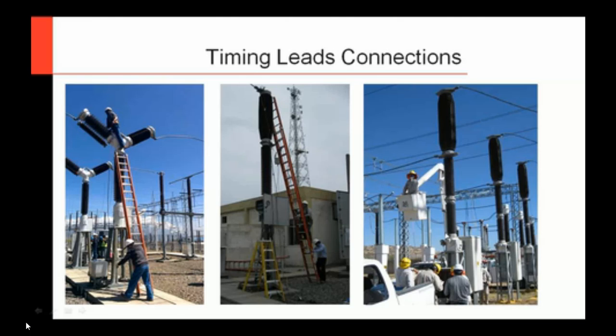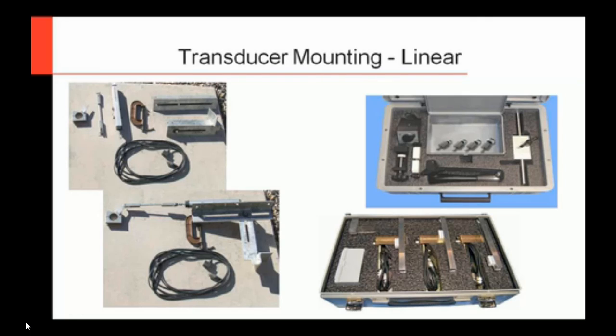Of course, the next thing and the most complicated thing with circuit breaker timing is the transducer. I wish I had an easy way to do this, but really each breaker has to be evaluated for its factors. Some manufacturers are very good about giving you pictures. Other ones, especially some older designs, you might have to figure out on the fly in the field.